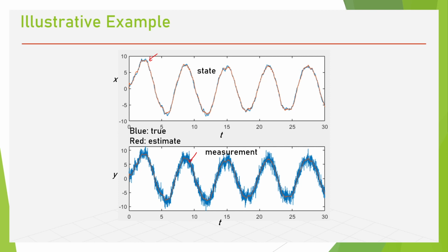because the controller gain is too high, especially when we have a derivative controller. I think you already learned in the control theory course, you already know the derivative is very sensitive to noise, because if we look closely from one point to another point with the noise, you can see the slope is very high. So it means the derivative term is very high. So feedback control using the direct measurement is not always good. Most of the time it's bad.